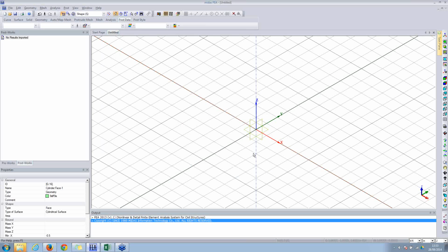There is another question about the concrete beams. What is the difference between the modeling technique of faces and solids in concrete beams? It's nothing but, if you want to do a 2D analysis of a beam, we use faces. Okay, we model the beams as a 2D face, and we apply all the loads in one plane, and all the boundaries in one plane, and we do a 2D analysis. This will give us the results in, say, the XZ plane.